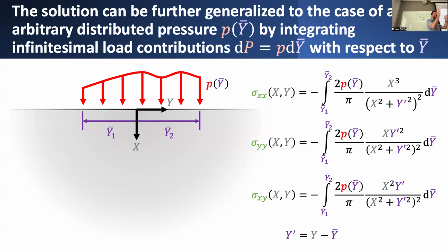And we can sum together all those contributions, and through superposition, we can figure out the resulting stress distribution, which is a combination of all of the different stresses that would result from a bunch of point loads distributed over some area, all summed together. In the continuous limit of doing that summation, you get an integral.